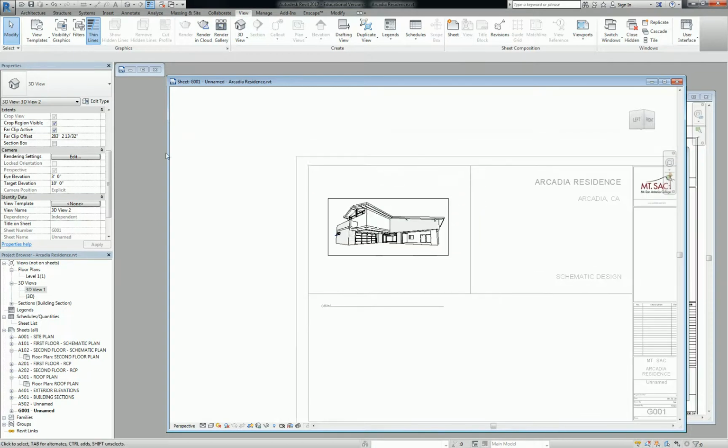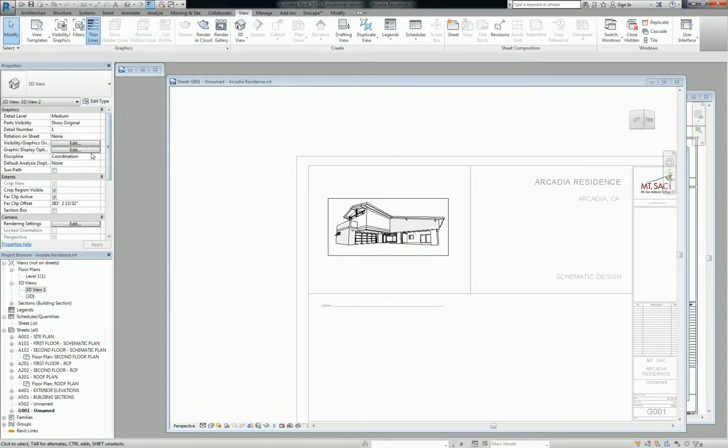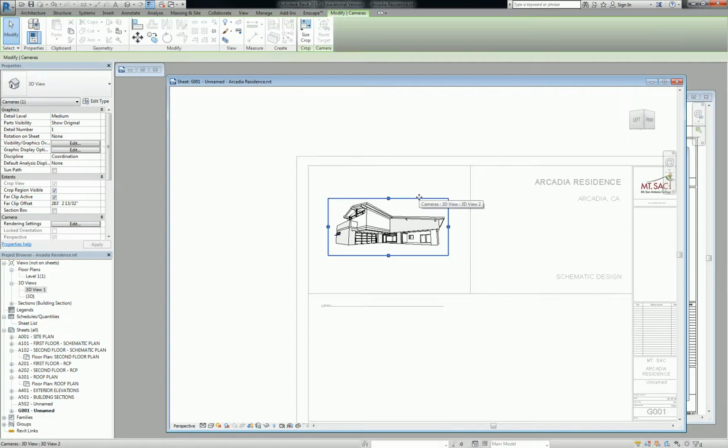But when I'm inside the view, you might realize that there isn't really a view scale, right? There isn't any 1/8 inch equals a foot, or 1/4 inch equals a foot, or 1 to 20, whatever. We need to manually set exactly how large we want this thing to be. So if you select this, you go to, I believe it was size crop.